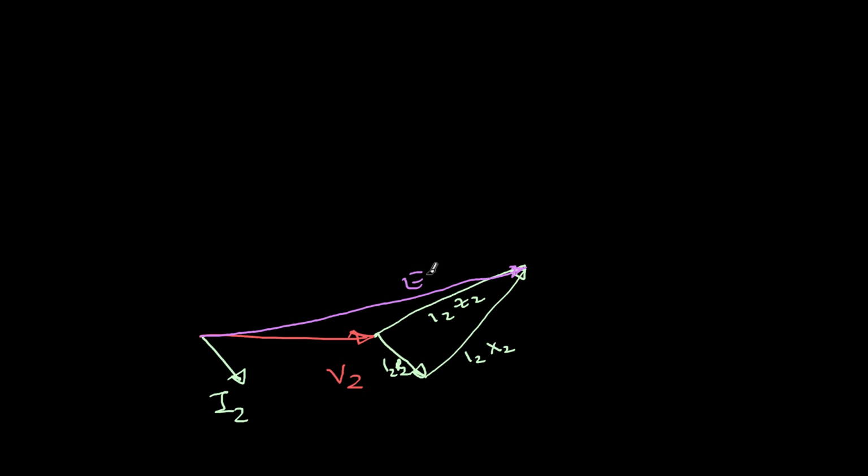E2. Now that I got E2, E2 is nothing but K into E1. So if the E1 I transfer to the secondary, it will exactly coincide with this. So therefore, to K into E1, again I will add one more resistance drop. This will be exactly parallel to this line. It will have the same angle. And then again, one more line like this.